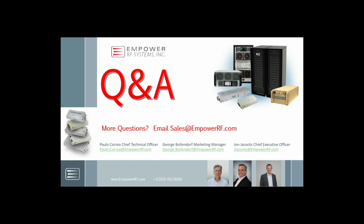When protecting against high reverse power, how fast does the protection loop have to act? Yes, again, here is what I said during the webinar. If your VSWR can cause voltage breakdown, you need to act in about 200 nanoseconds.